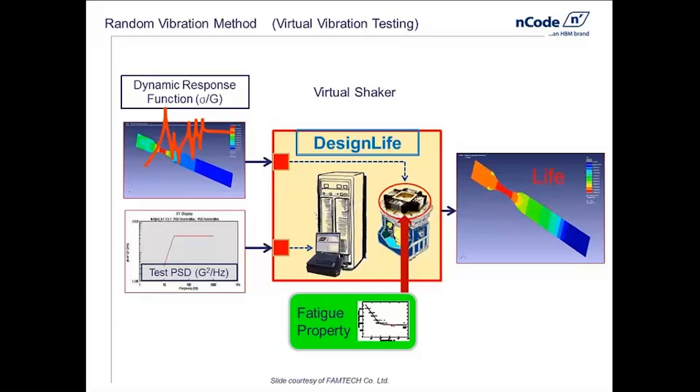And once I have stress cycles, I can use that along with a material fatigue curve to calculate individual cycle damages and hence total damage on the part in terms of minutes or hours of operation. So the result now is a contour map of life in terms of time it takes the part to fail.